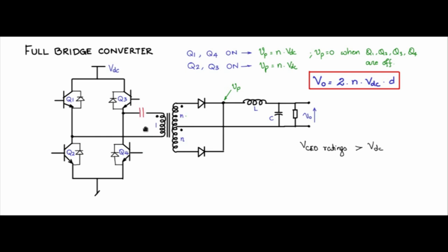Now, in the case of the full bridge converter also, we see that there is a requirement for solving the flux walking problem. Wherever this kind of a situation occurs, where you are having switches, practical or non-ideal switches, and you are having a winding connected in this fashion, there is a chance of an average voltage occurring across the V primary.